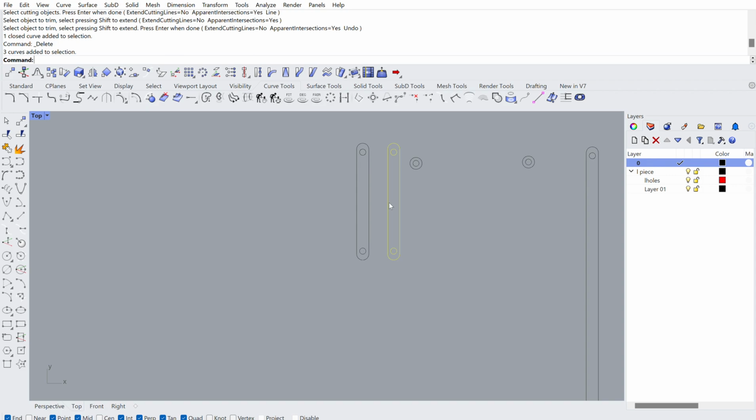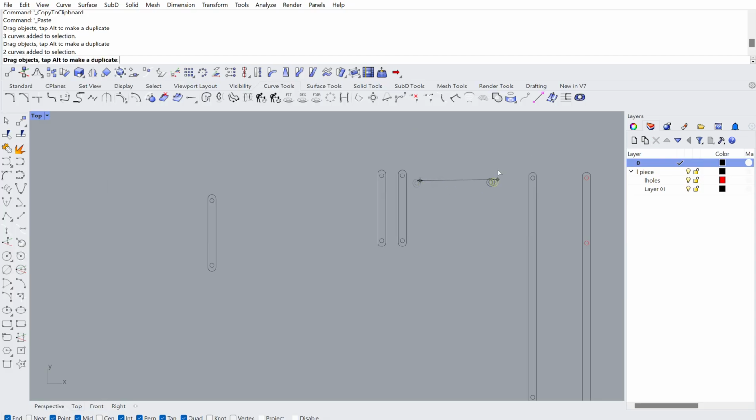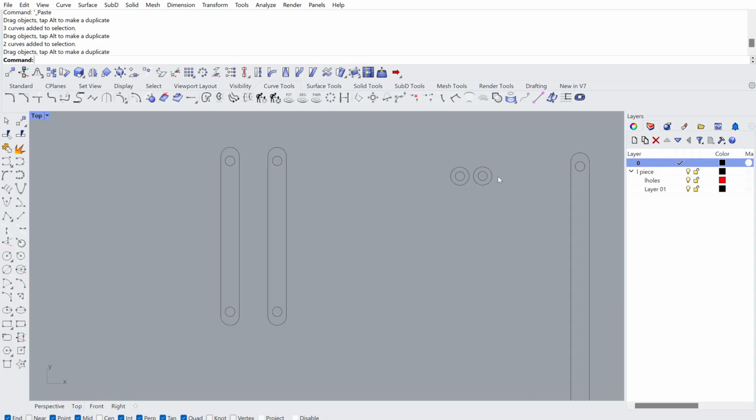But I actually find the best way of dealing with past versions is you just make a copy and move it over somewhere else, if you need to maybe reference it again later. Because Rhino is direct modeling, it does not use nearly as much memory as something like Fusion 360 or SolidWorks, which are constantly doing all this parametric work to calculate and figure out that your model is still working. Rhino does not need to do any of that, and therefore it's very cheap to make more geometry. And that does make it very powerful in certain ways, and it makes it a certain kind of tool. So I definitely find that Rhino is a good tool for these kinds of things.